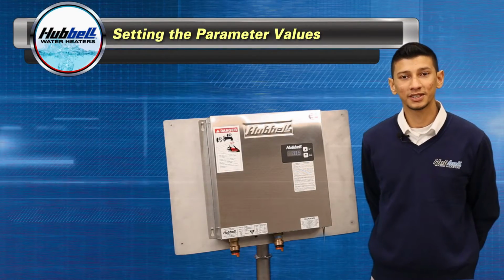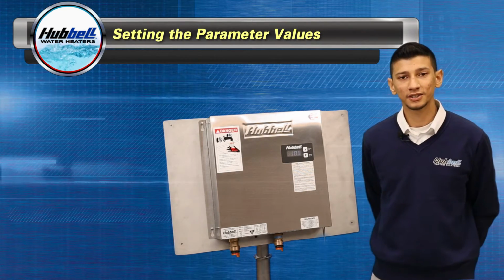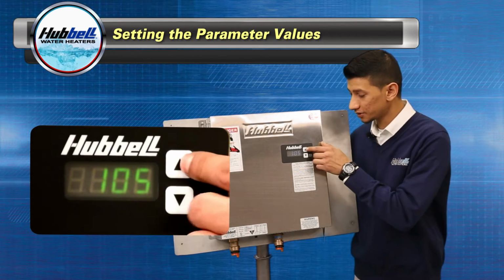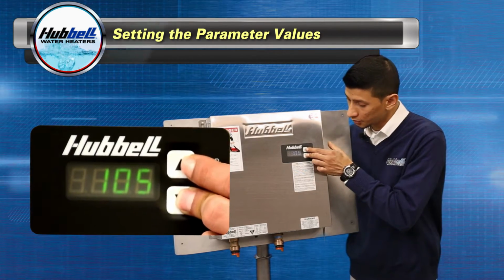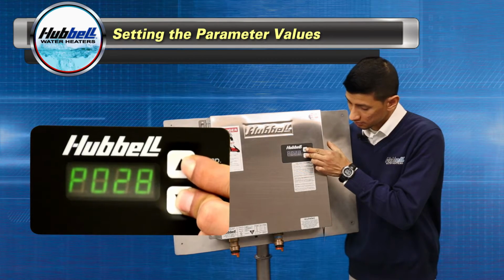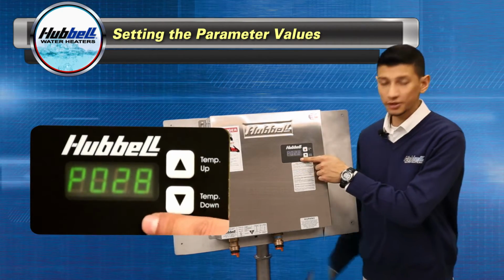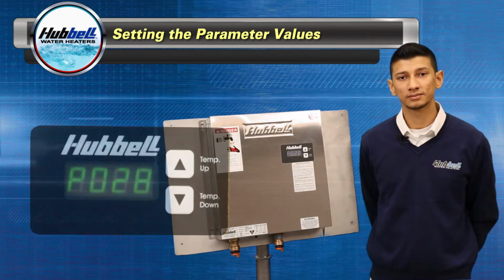Today I will discuss the meaning of each of the parameter values in the configuration menu. As discussed in previous videos, in order to get into the configuration menu, you're going to press and hold the temperature up and temperature down button simultaneously. You're going to press and hold until P0 and two numbers come up on your display, and you let go. The first parameter you see is your power setting. That represents the kilowatt of your heater.